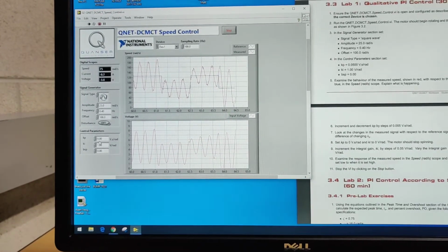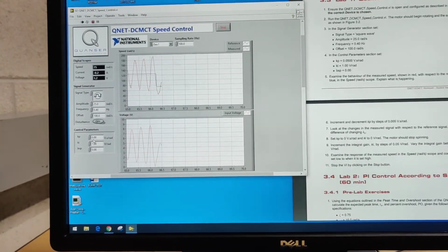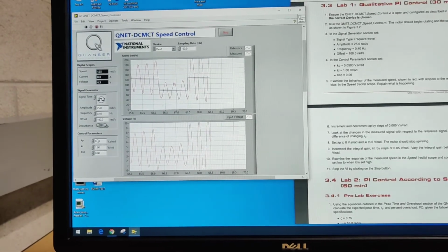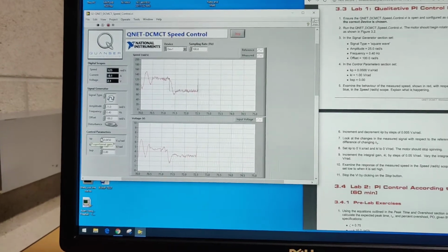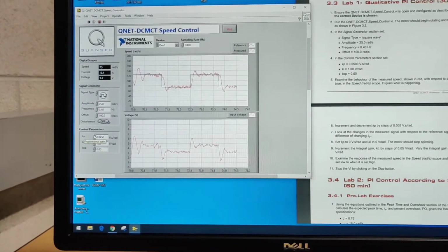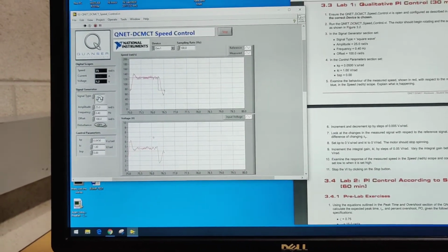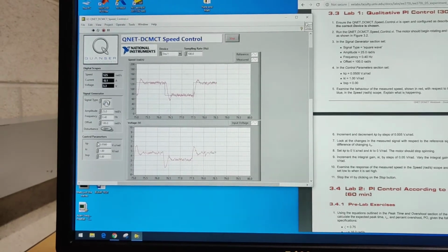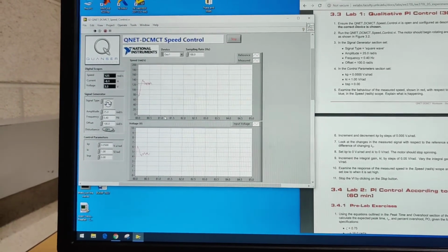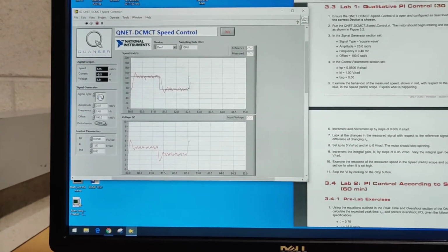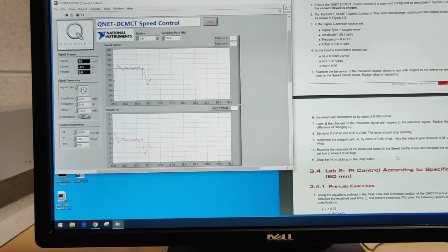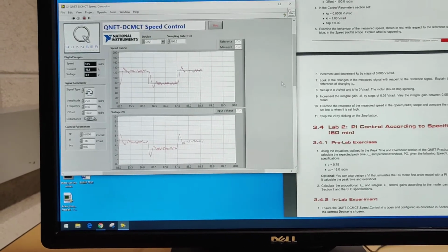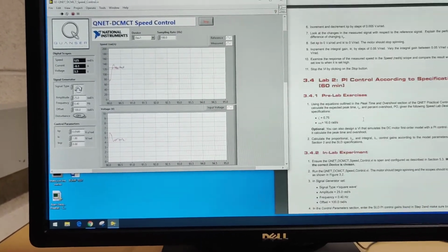What you need to do is increase this a little bit to reduce the damping ratio, and figure out the exact Kp and Ki to make it more consistent with the simulated, or reference, waveform. Okay, so this is for part 1.